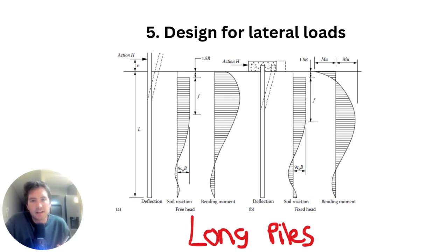And again, these bending moments are very difficult to work out. It's not like a simply supported beam with wL squared over 8. It is dependent on the relationship of the stiffness of the pile to the stiffness of the soil. So I think it's good to know how the soil reacts and be able to sketch the basic bending moment profiles for this stuff.